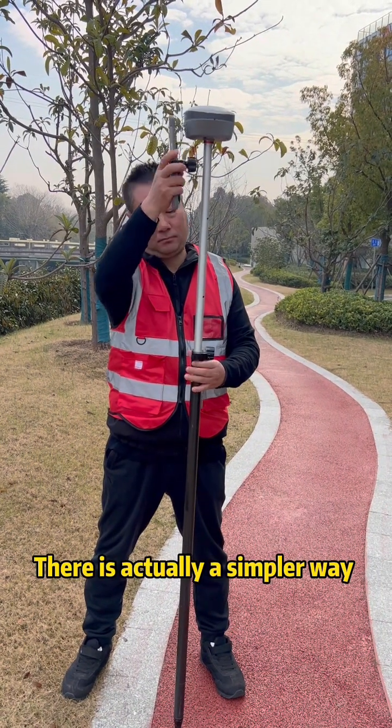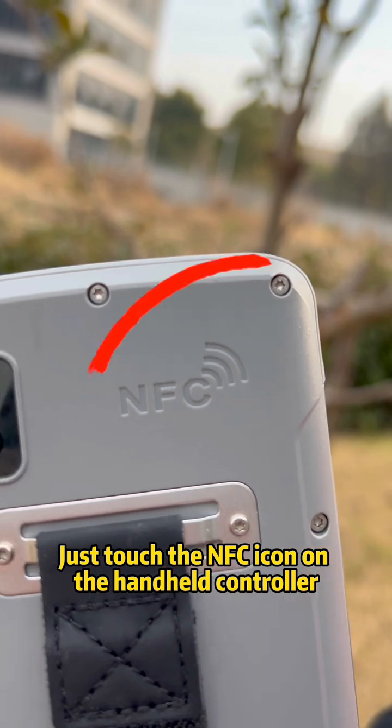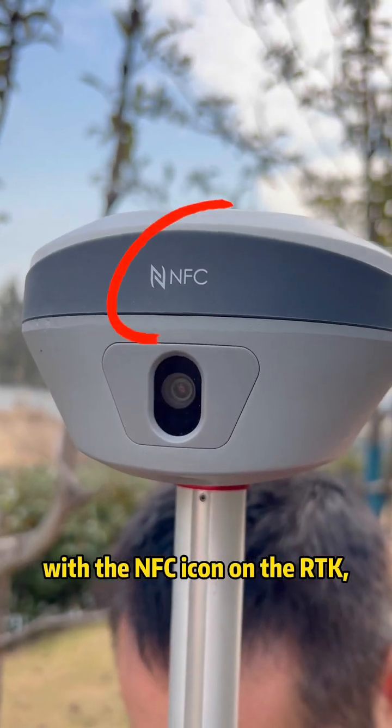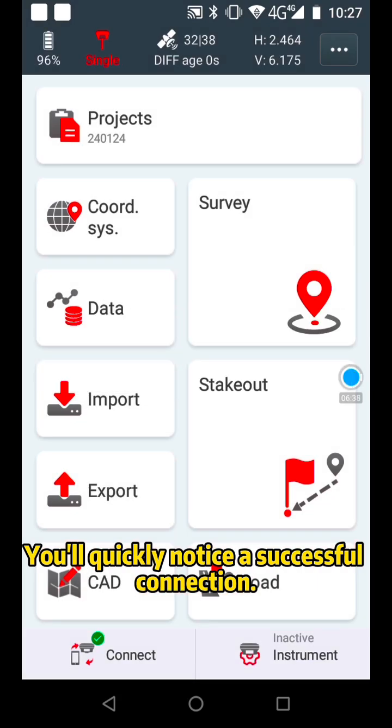There is actually a simpler way to connect the receiver with the controller. Just touch the NFC icon on the handheld controller with the NFC icon on the RTK, no additional settings required. You'll quickly notice a successful connection.